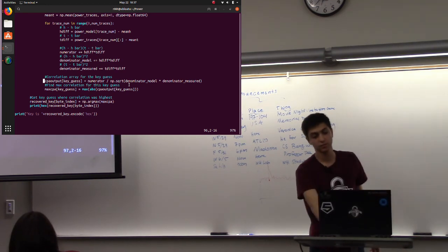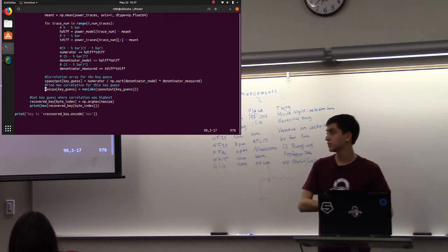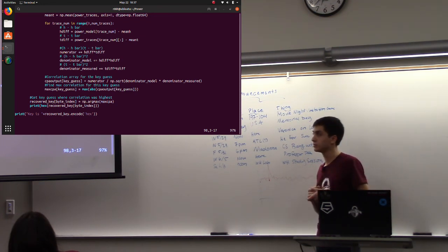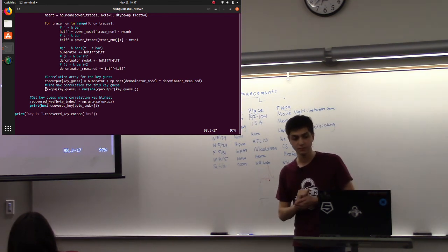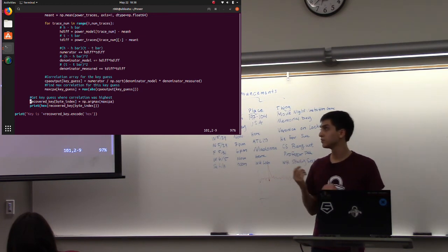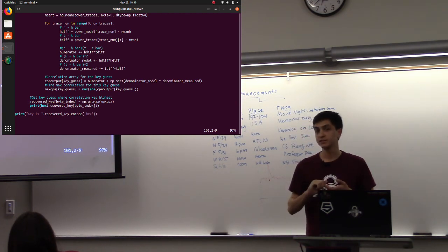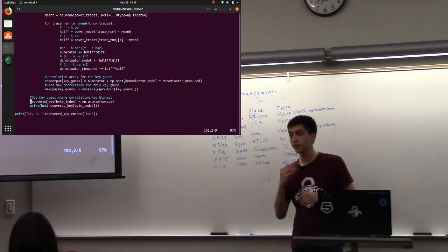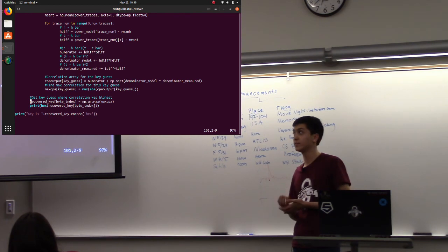So that brings us down to the max CPA, which is here. It's just that max point, and for that key guess, that's our maximum correlation. We go through all key guesses and find a maximum correlation for each one. Then at the end, for that byte of the key, we find the max of all those maxes, and say that's our key guess. Then we go to the next byte and do all that again, until we have 16 bytes.